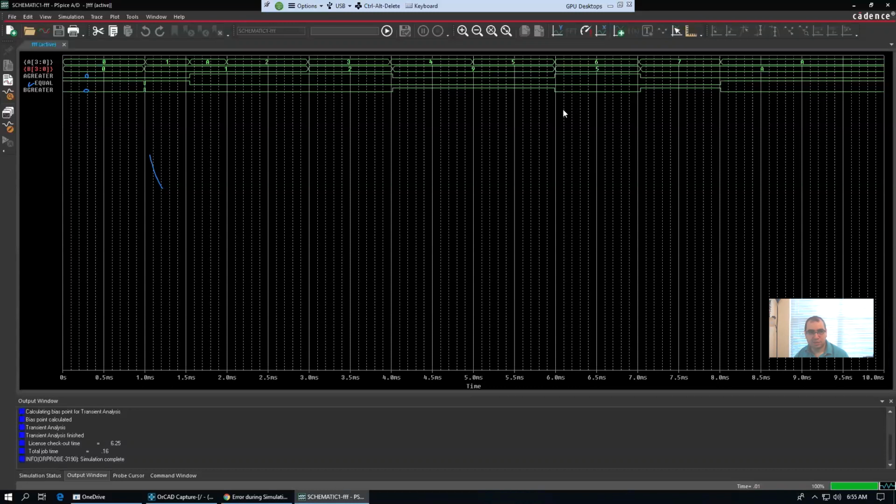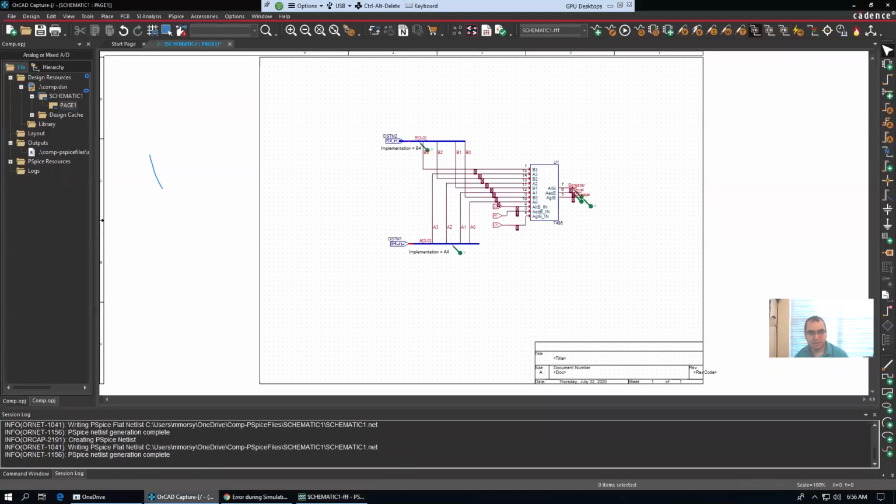So that's all for this tutorial. Hopefully that gives you an idea how you can build a 4-bit comparator. If you want to build an 8-bit comparator, you need to cascade 2 of these. And also, what will change here? Instead of a 4-bit stimulus, you need to have here an 8-bit stimulus. So just select the one that has 8 here, and then you can configure it similar to what we have seen here.